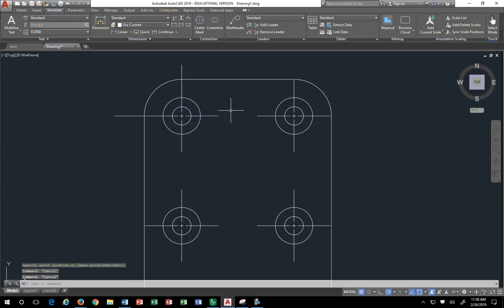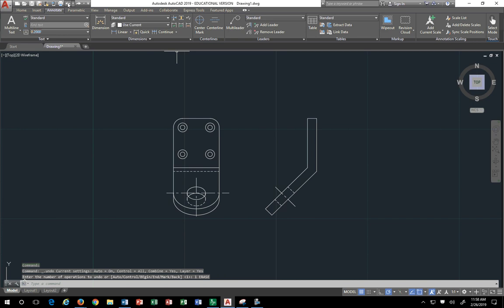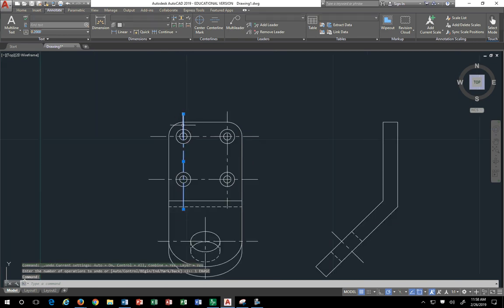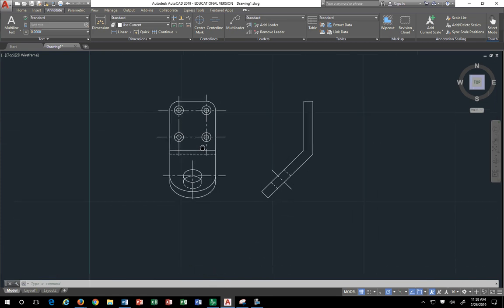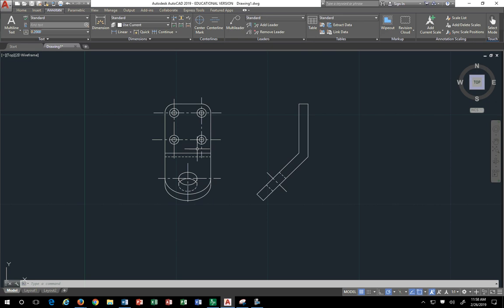Plus, I have a preference of showing my client that everything is lined up together. This line needs to be lined up with this line. This line represents the center of these two holes, and that's why I prefer just drawing center lines. But yes, when you do that, you lose the ability to control those perfect little center marks. Okay? I'm letting you know that it's okay with me. Somebody else might not like it, but in my case, I'm good with it.